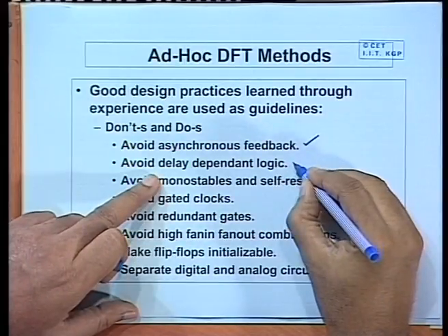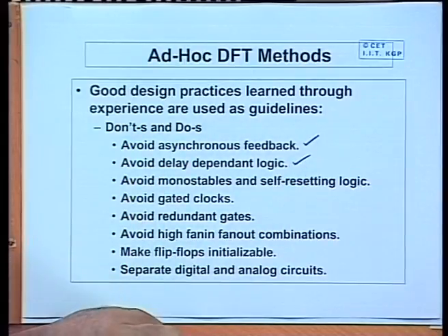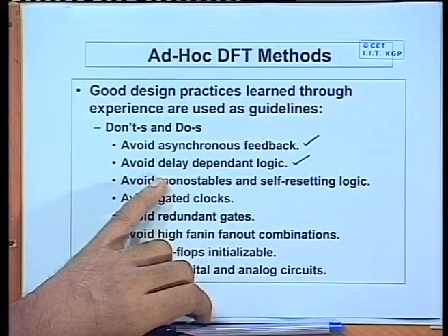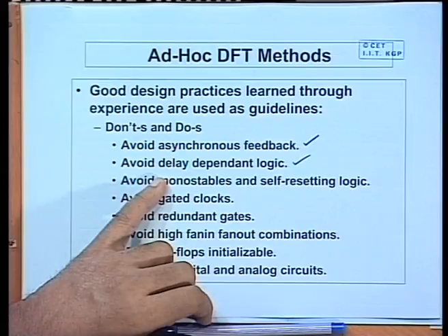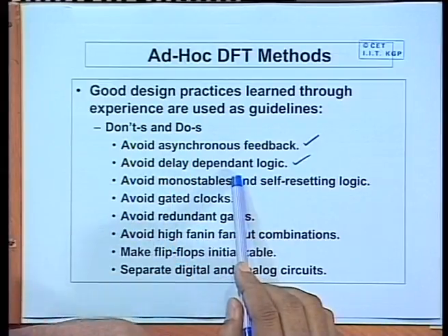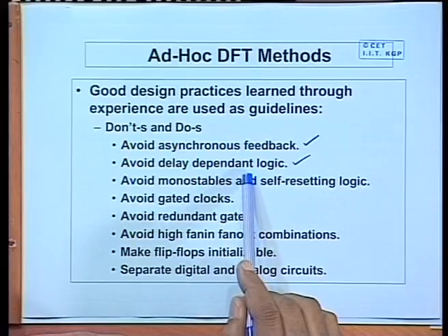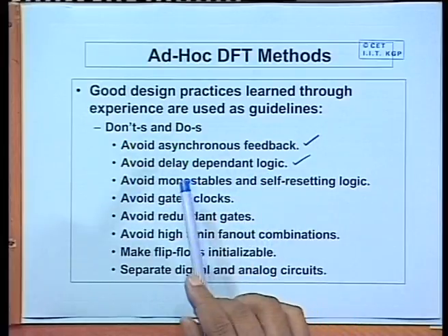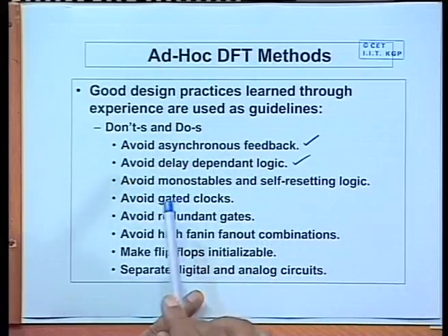Avoid delay dependent logic. Sometimes we design circuits where the delays of the individual circuit elements are made use of in order to achieve some logic. For example, for generating a very narrow pulse equal to the delay of 1 gate or 3 gates and so on. So, you do not use those things.